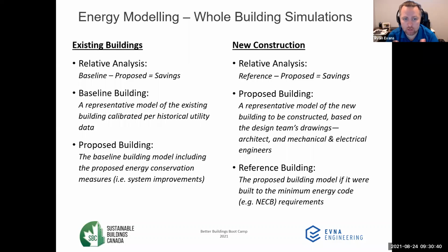When we improve lighting, let's imagine that we have an older building and it still has fluorescent lighting. It hasn't been converted to an LED system yet. Those fluorescent light ballasts actually produce heat. So when we start retrofitting those lighting systems to a more energy efficient LED system, they'll use a little bit less energy, and consequently you produce less heat that actually aids in the space heating in the building. So by having less heat generated by your lighting system, it actually influences your cooling system positively because there's less of a cooling load. However, it has a slight negative impact on your heating system because now your heating system has to make up that difference.